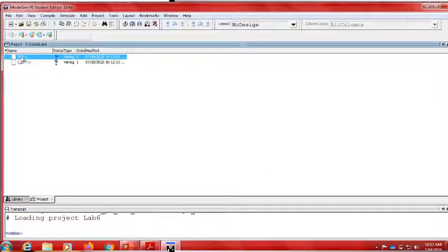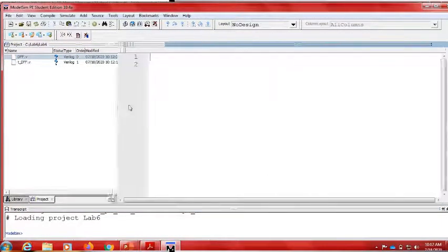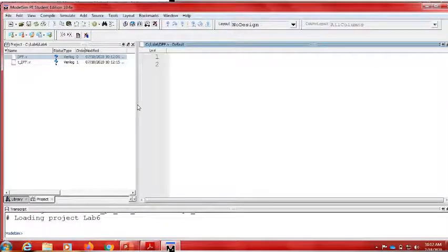Now coming to our main file, we define the basic structure, what will be the port list and the interconnections which you have to use in your lab session. So we'll define the keyword module, the flip-flop, and inputs are D and clock, and outputs are Q and Q prime. And then we're going to end this with endmodule.